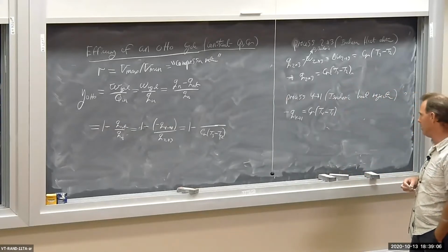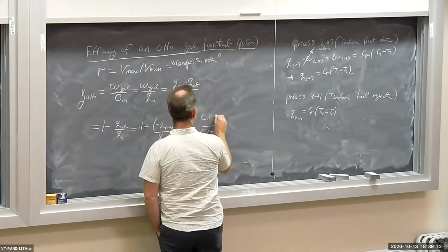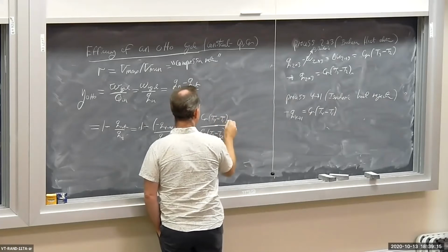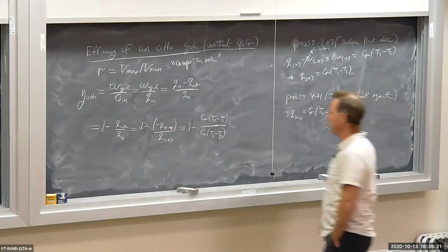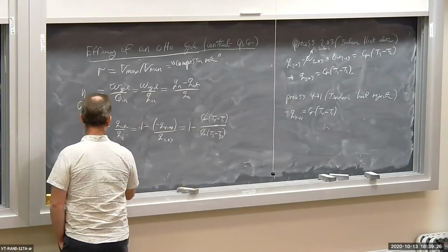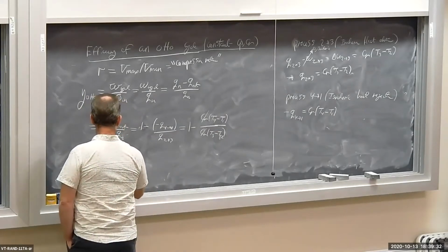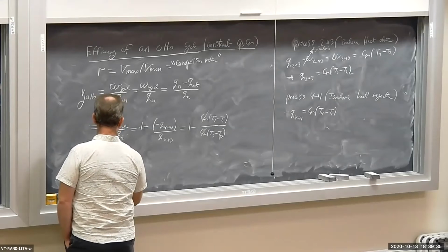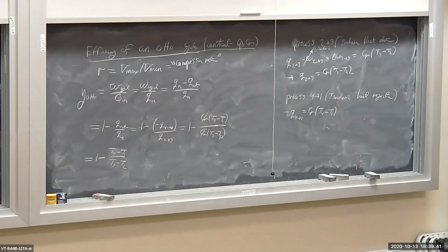And that's out positive. Okay, so the numerator then is CV (T4 minus T1). Now the CVs cancel out, and I get 1 minus (T4 minus T1) over (T3 minus T2). I got a bunch of temperatures in there related to the heat transfers in and out of my system executing an Otto cycle.